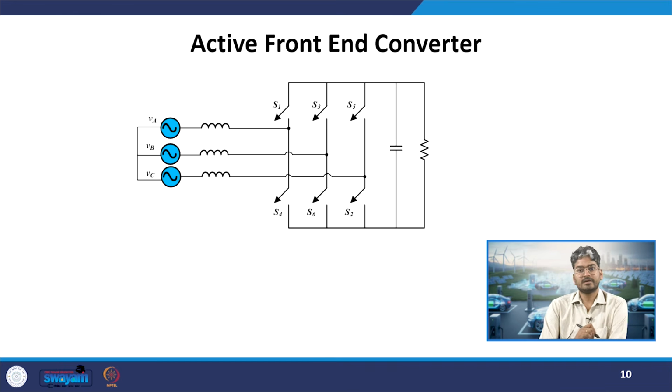Then we will now see if I want to increase the power rating of my charger. So, I will shift into three phase supply. Where I want a fast charging operation, I have to connect the charger to a three phase supply. If we have a three phase supply, then we use a three phase VSI, voltage source inverter.